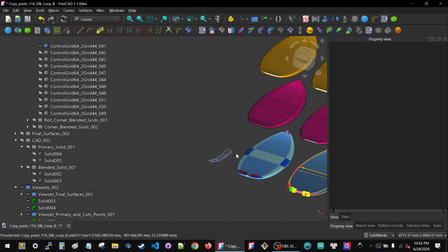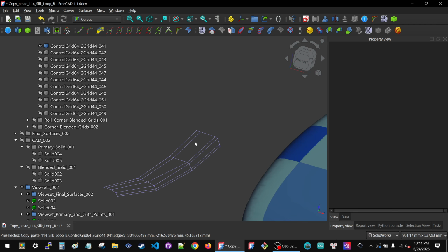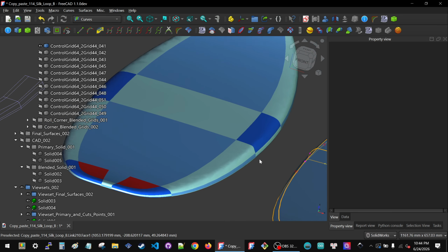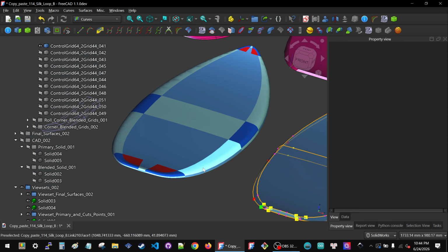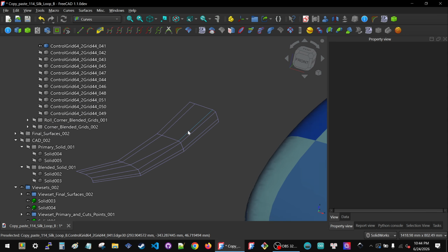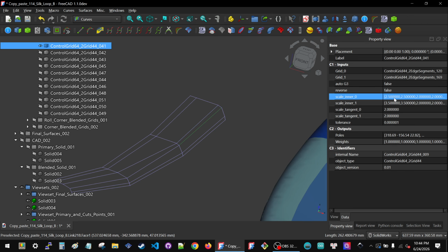So the cutting points force you to have a given size of the blend, but you can work inside the blend to effectively have a varying fillet radius within the blend. And it can be along the whole edge of the blend, which will then intrude halfway into the next double blends, or it can be on half of the edge blend and then go into the next double blend. Now, one thing you have to be careful of is, okay, I showed you moving an entire row. I showed you moving 2 points halfway across a row.